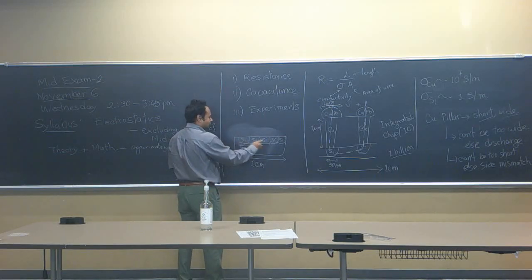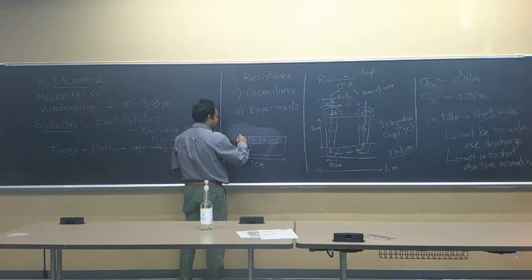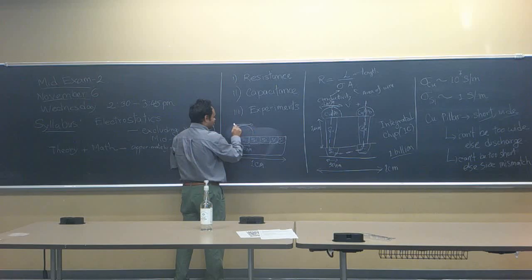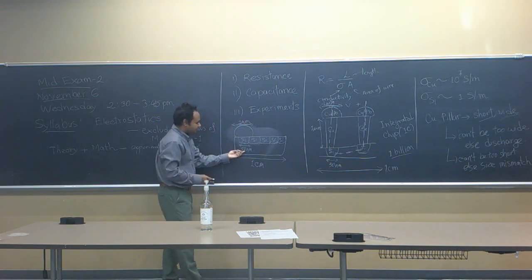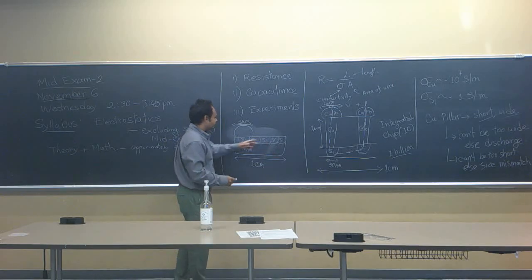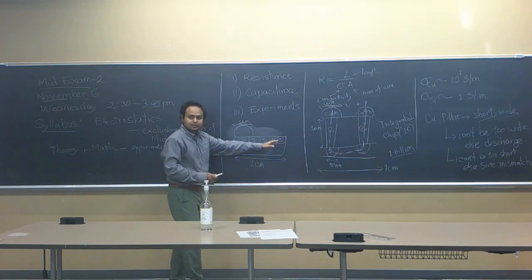Let's say I want to make copper pads on all of these devices, and I make a 1 micrometer pad. That pretty much touches the other die. So you understand that you cannot put a 1 micron pad on top of something which is just 50 nanometers. You don't have the space. This is why we have to make connections with all of the silicon devices differently.